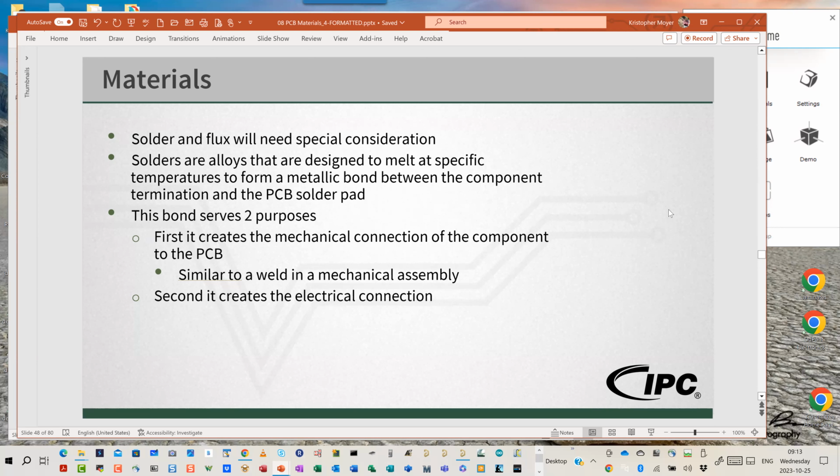The fabricator will typically tell you what their standard panels they keep in stock are. And if they don't list them in the capabilities, you just call them. But in all honesty, if you stick with 18 inches by 24 inches, at least here in the States, that is the bread and butter that everybody does. There are some other panel sizes smaller than that, and if you need to go larger than that, you go over to mass lamination facilities where you're paying extra money to do extra large panels.